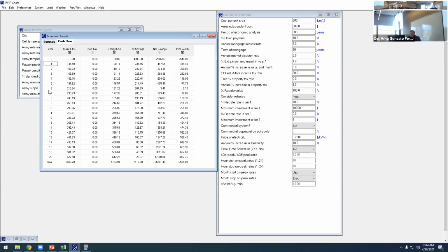So with this analysis, at the 6th year, we start earning money because we have recovered our investment, and because of the savings that we are getting with this PV array, we start earning money and saving money. And at the end of 20 years, my positive balance is 17, almost $18,000.